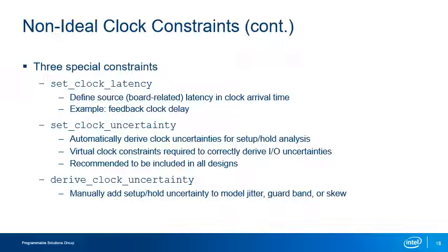The next special clock constraint is derive_clock_uncertainty. This command is an Intel SDC extension that can automatically derive uncertainties inherent in clocks used in supported devices. It adds uncertainty for data transfers within a single clock domain and for transfers going between two clock domains.